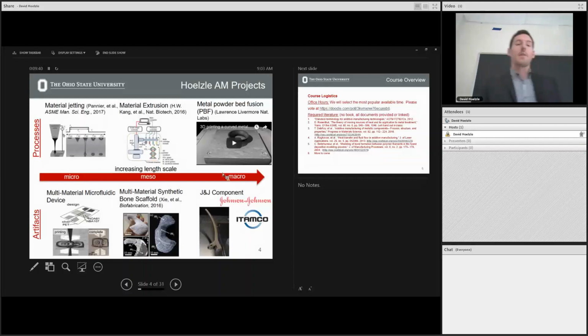So one thing that we look at in my lab is material jetting additive manufacturing processes. These are processes that are like inkjet printing. You've seen inkjet printers, of course, in your house. Those make features on the order of around 30 to 100 microns. We look at additive manufacturing processes for the production of electronics and microfluidic devices, where we have features on the order of 1 micron. That's less than 1/20th the width of a human hair is what we fabricate. If you look in the very small regions of the silicon wafer, you can see some of the things that we've made, and that's what we look at controlling.